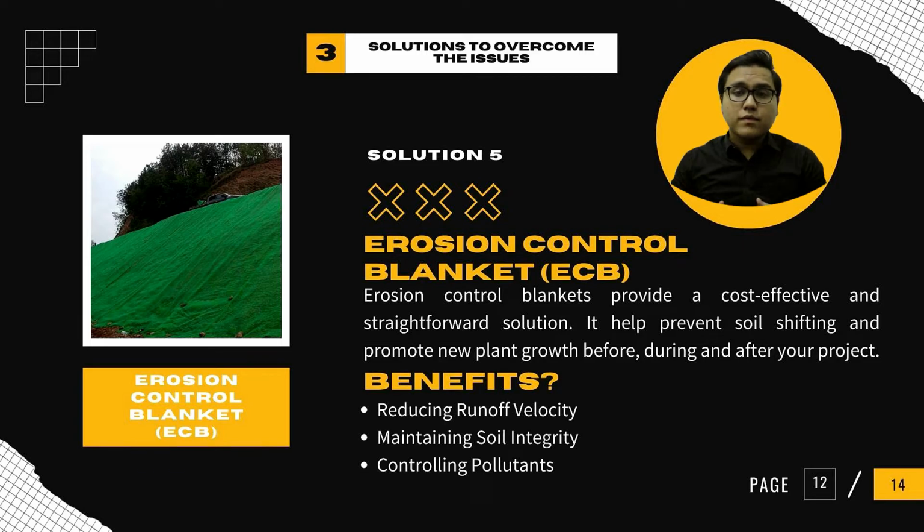ECB can protect soil from the impact of precipitation and also the overland flow and retain the moisture to facilitate establishment of vegetation. When sites use erosion control blankets, the vegetative layers absorb the energy of the rain as it hits them. By doing so, they reduce the velocity of the subsequent runoff. The slower, less forceful runoff carries away only a small amount of sediment.